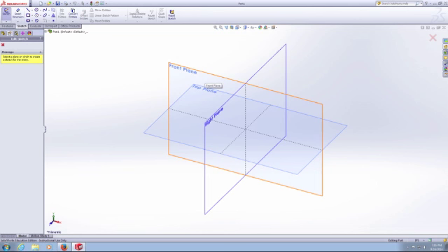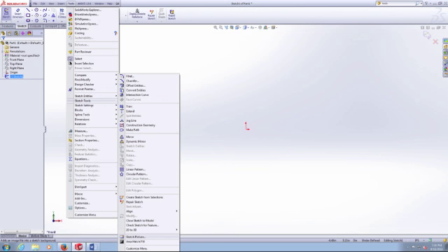of manufactured parts. So the first thing you have to do is open up SolidWorks and select the plane on which you would like to insert your image. In this case, I'll be working on the front plane. Once we've selected the plane, we can insert our image.